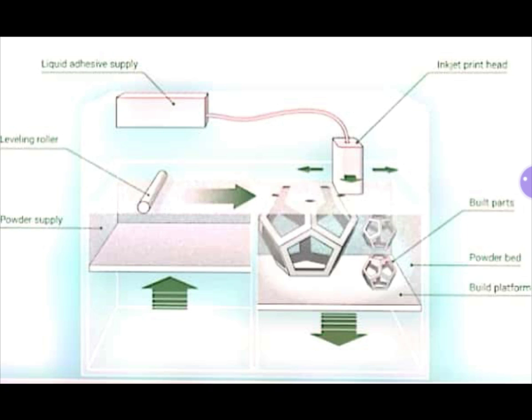After binding the powder particles at particular places on the build platform, this build platform is then lowered by a distance equal to the thickness of the powder laid on the platform, and again the process is continued.